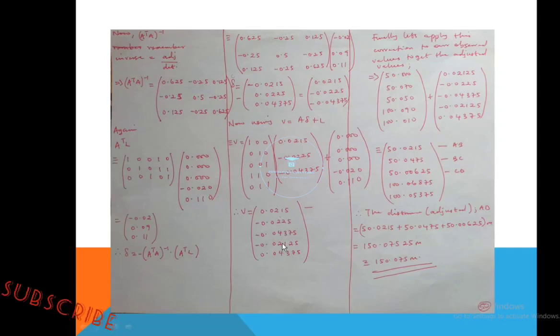So this is where you now have what? The residual you are going to apply to what? Each of the observed values. Finally, let's apply this correction to our observed values to get the adjusted values. Are we together? So these were the observed values. Remember that for AB we had 50, for BC we had 50.07, for CD we had 50.05, for AC we had 100.09, and then for BD we had 100.01, right? Now plus all this V, like the residual, plus the residual.